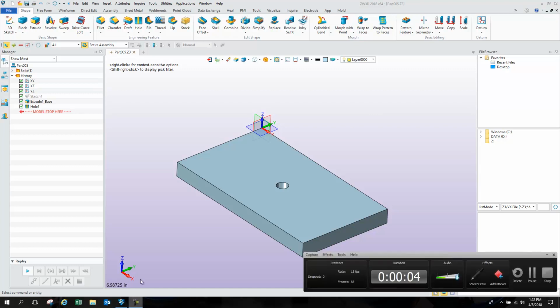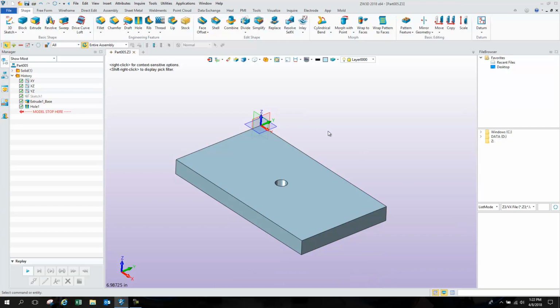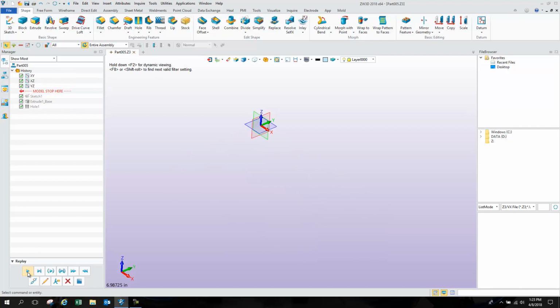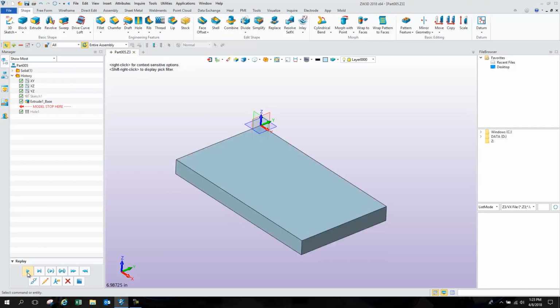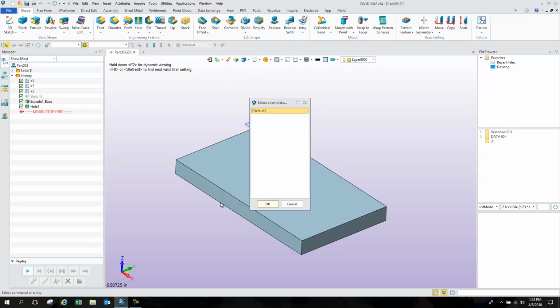Okay, so we're going to do an entry to milling demonstration video here. I just got a simple plate, create a little sketch for, create a solid extrusion down, and then put one hole in it. If I want to go ahead and machine this, I right click, say let's go to a CAM plan.